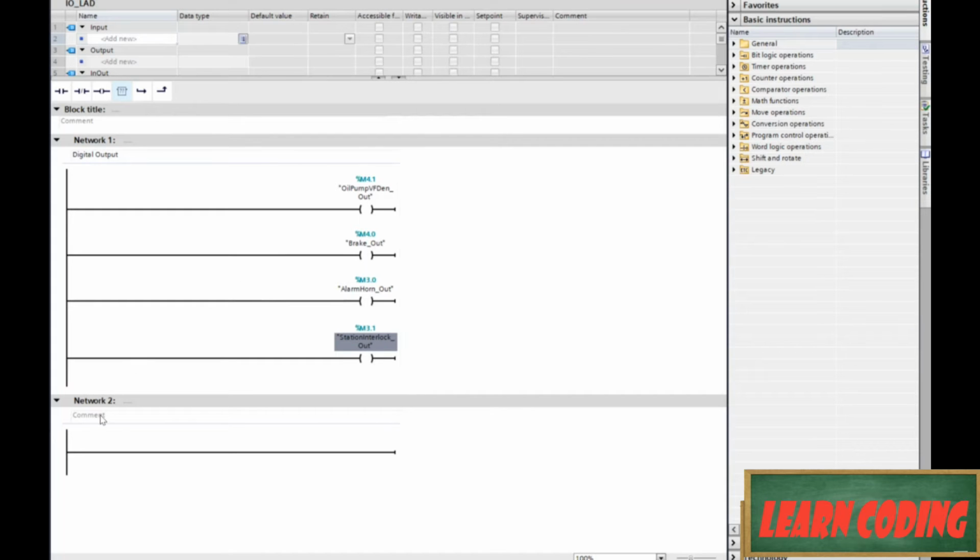Now let's go down here and let's get to work on our analogs. And we've got analog ins and analog outs. Let's go ahead and start with our analog outs. So analog outputs. And first one that I know we've got is we're controlling our VFD. So we need to be scaling a signal out to our VFD. Well, while we're doing this scaling, I'm going to go ahead and set up a function block so that I can do my scaling in one block rather than use 2.